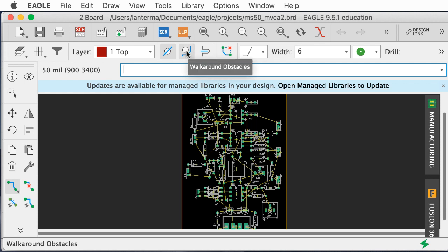And the reason you want to do this is that you will often have a very terrible layout of parts, and until you get some practice with it, you won't notice it if you use something like an auto router, and you'll be going all over the place. The other reason, if you do a layout by hand, you sort of get an opportunity to spread the traces out a bit in a way that makes it easier to debug the circuit later. So you can see on both sides of the PCB, you can see the traces and follow what's going on.